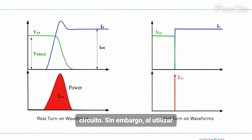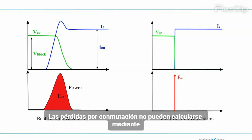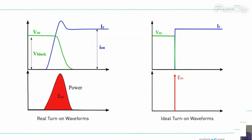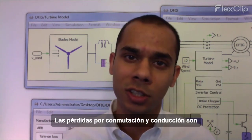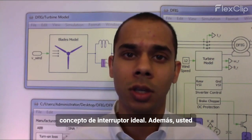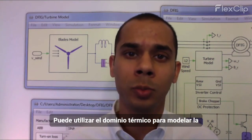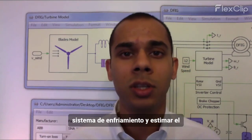However, when using instantaneous switches, there's no information about the transient waveforms during turn on and turn off. Thus, switching losses cannot be calculated by multiplying the voltage and current. In this video, we will discuss how the switching and conduction losses are modeled in PLECS in conjunction with the ideal switch concept. Additionally, you can use the thermal domain to model the thermal structure of a device and its cooling system and estimate the associated temperatures.